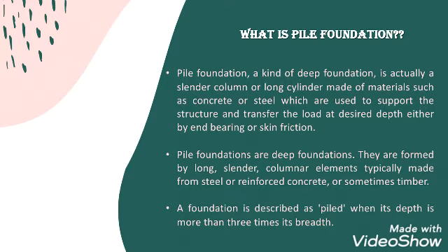Pile foundations are deep foundations. They are formed by long, slender columnar elements typically made from steel, reinforced concrete or sometimes timber. A foundation is described as pile when its depth is more than 3 times its breadth.